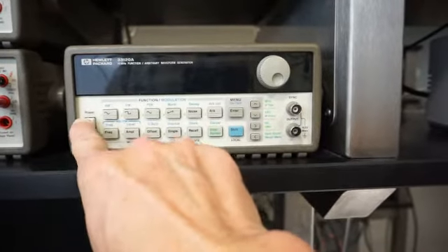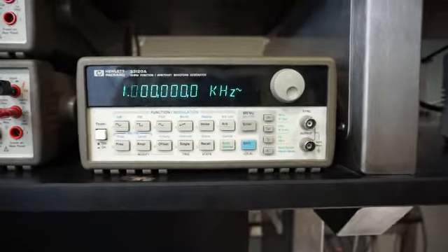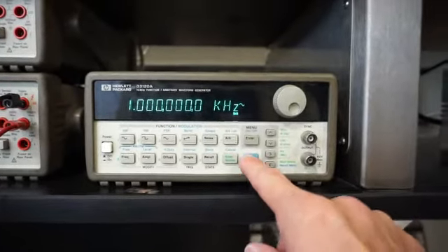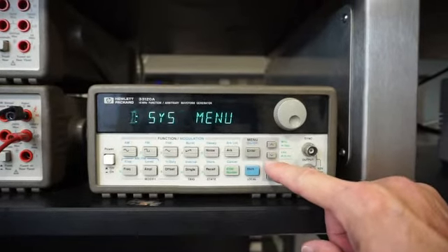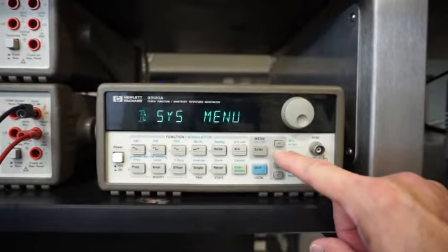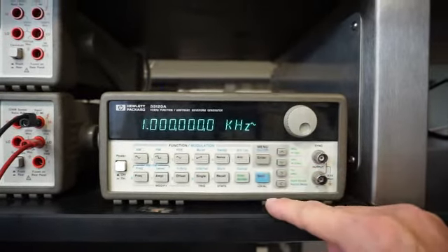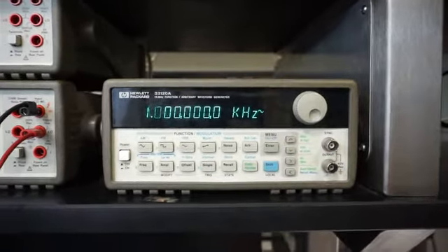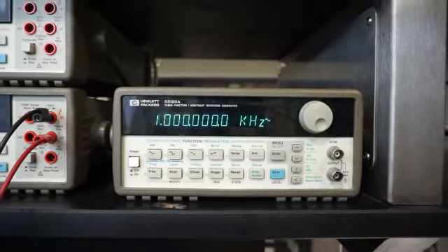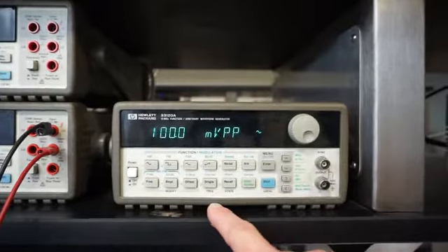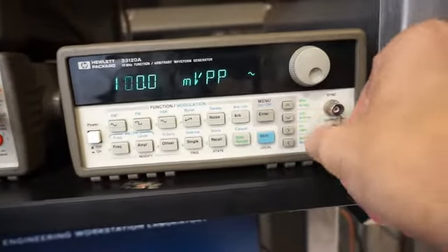The function generator is a benchtop tool that can generate periodic signals. It behaves like a time-varying voltage source, but by design it has a 50 ohm internal series resistance. This 50 ohm resistance will act as 1/2 of a voltage divider when a load resistance is connected. The default mode of the function generator is to assume that a 50 ohm load will be attached. Therefore, the amplitude readout will only be 1/2 of the actual peak-to-peak voltage generated.